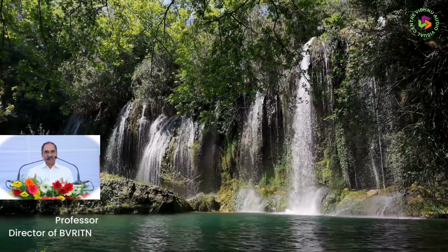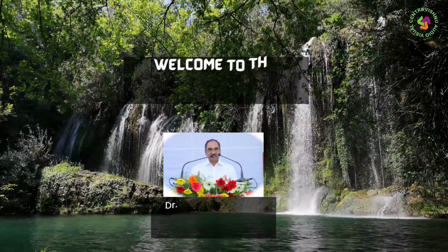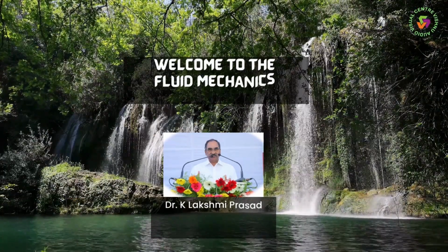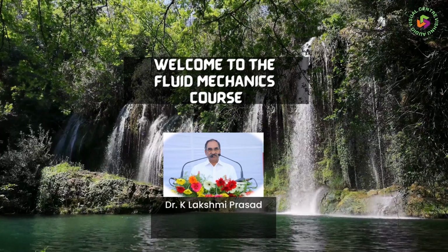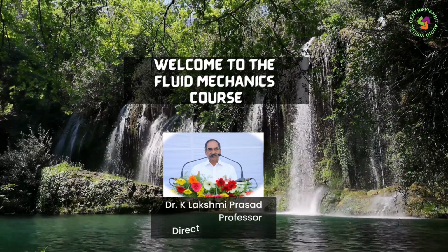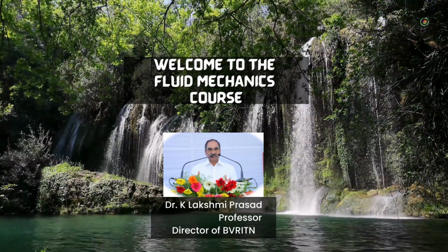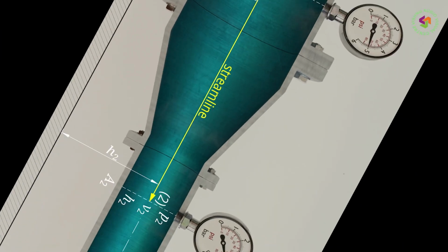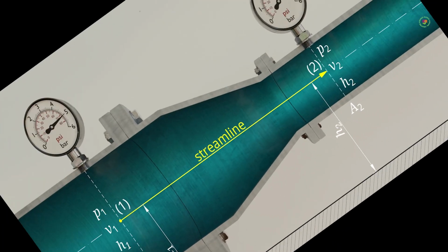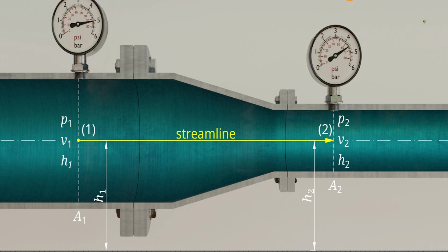You know, the Bernoulli's equation is nothing but the energy equation, which states that for a steady, incompressible fluid, irrotational flow, non-viscous fluid, the total energy remains constant. The total energy is nothing but the pressure head plus the velocity head plus the datum head is equal to constant.